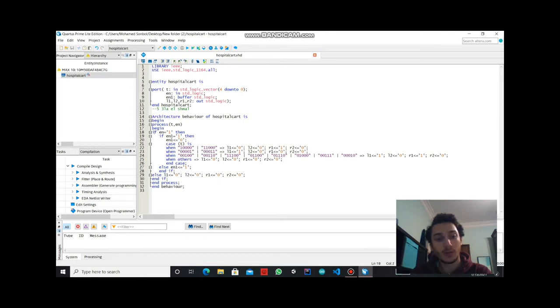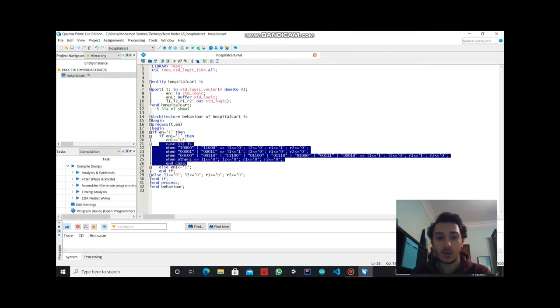Second, after checking for the proximity sensor, we check for our signal that we created. If it is equal to 1, then we set it to 0 and we move on with our code. If it is not equal to 1, then we just set it to 1 and do nothing, basically skipping a clock cycle, so halving the amount of time the motors are working and decreasing the speed of the car.